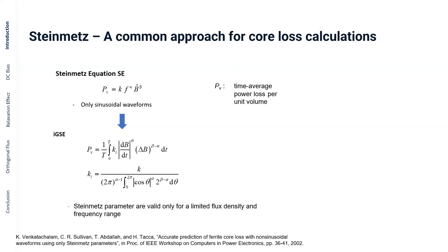But if you do this, then it should be okay. So whether the Steinmetz equation is okay at high frequency depends mainly on how you fit the parameters, at which operating points. You have to then also choose high frequency operating points. Now, having said this, there are some other effects happening at very high frequencies, which are not covered by the Steinmetz equation, like dimensional resonance, eddy current effects, if you have very big core sizes, things like this. So at some point, at very high frequency, this equation might not be good enough anymore.